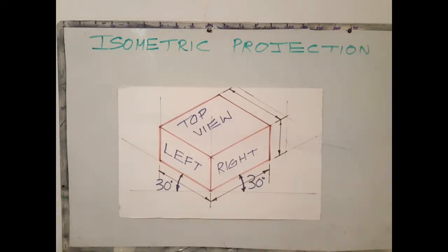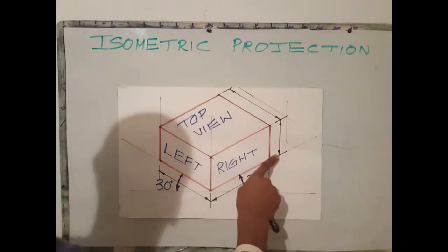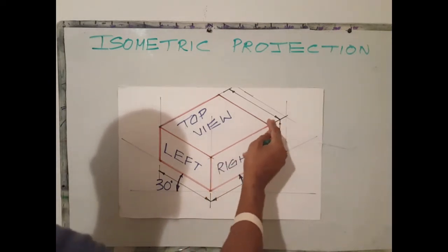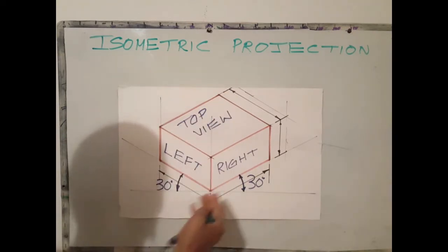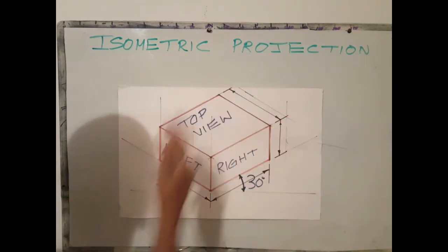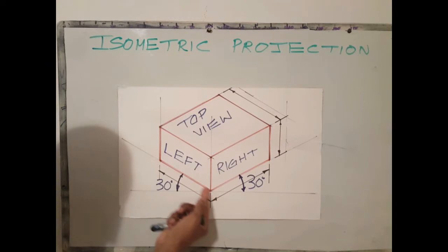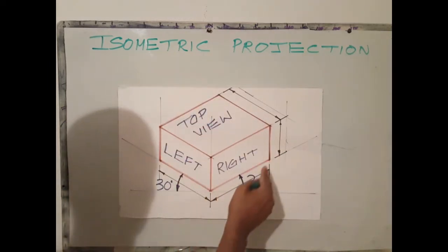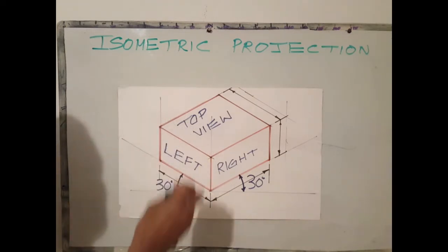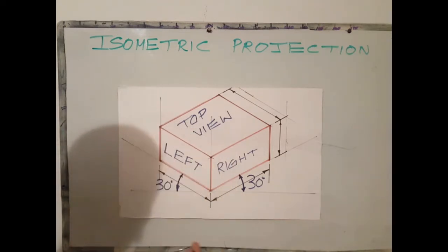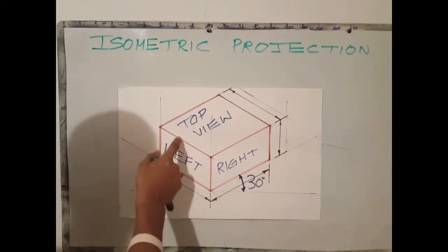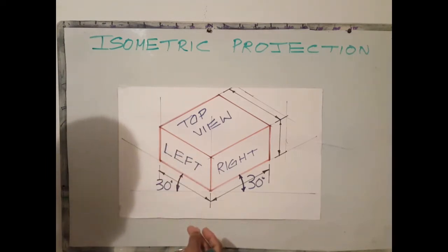Tip number 5. Lines on the isoplanes are always parallel. As you can see, first iso line is also parallel to this, parallel to that. So all these right isoplane lines are parallel. In like manner, the left isoplane lines are also parallel. The vertical lines, they're all parallel once they're in the isometric plane. There are cases where lines are drawn within the isometric planes. In cases like those, you plot those points.